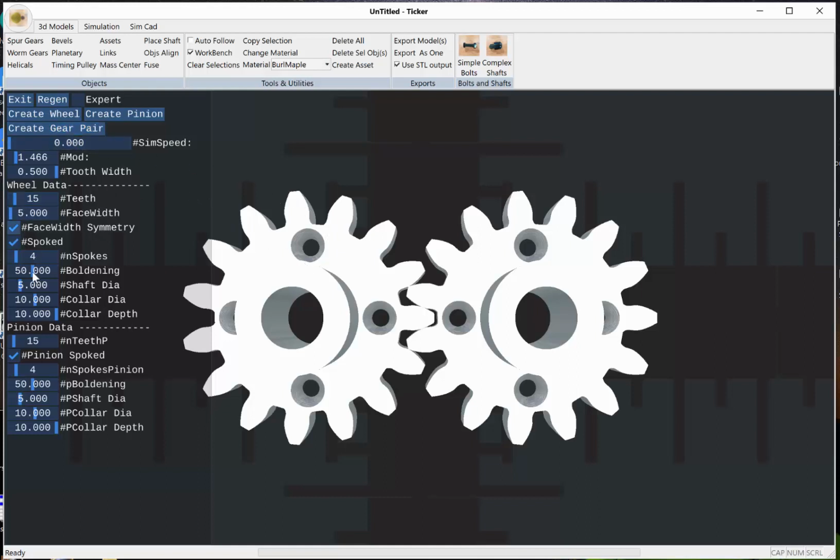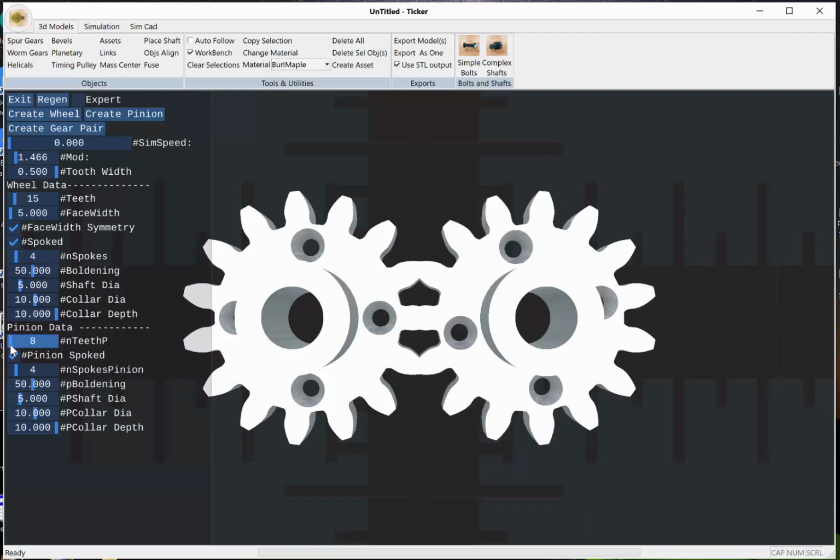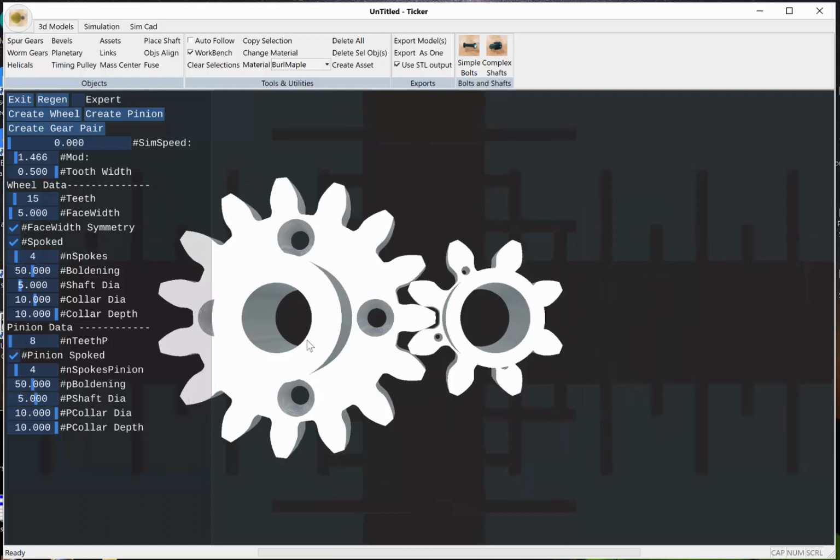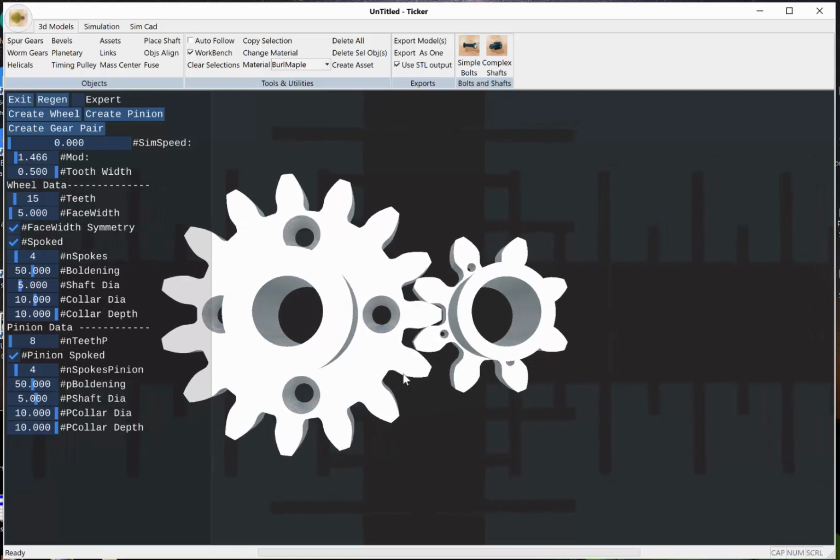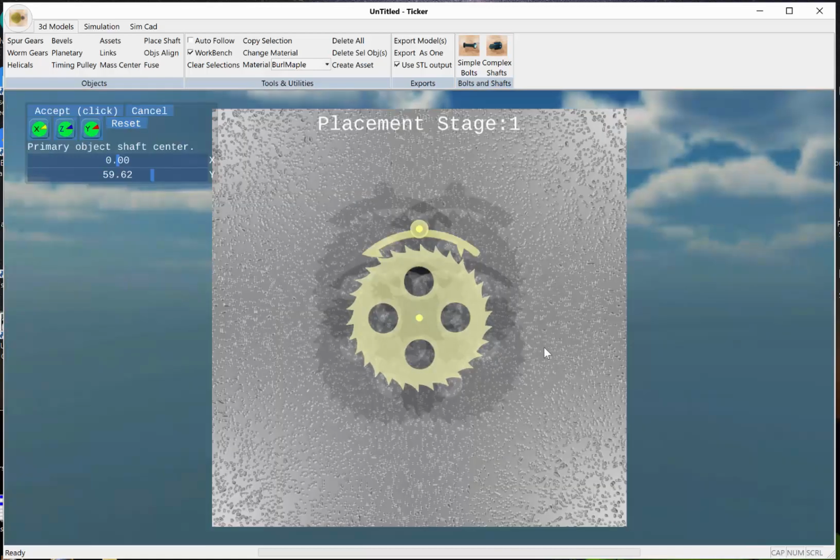And you want a small number of teeth, as small as what you figure you can get away with to drive your escapement wheel. This is because you're trying to get as much time as you can out of whatever weight train you're putting on. So you'll normally have a small gear on the weight train side of your ratchet. So I will create that pinion.